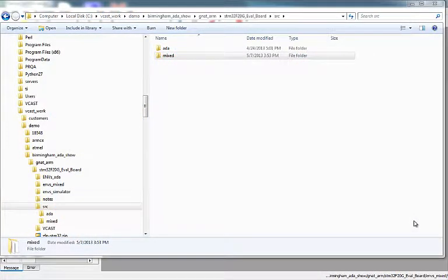This is a presentation of VectorCAST working with the AdaCore GNAT compiler for ARM Cortex-M3. We will show how to use VectorCAST to instrument source code to obtain coverage from functional system testing, and then how to build unit tests to verify functional correctness and increase our test coverage up to the 100% mark. And then finally, how we can take advantage of our test cases over the application lifecycle.